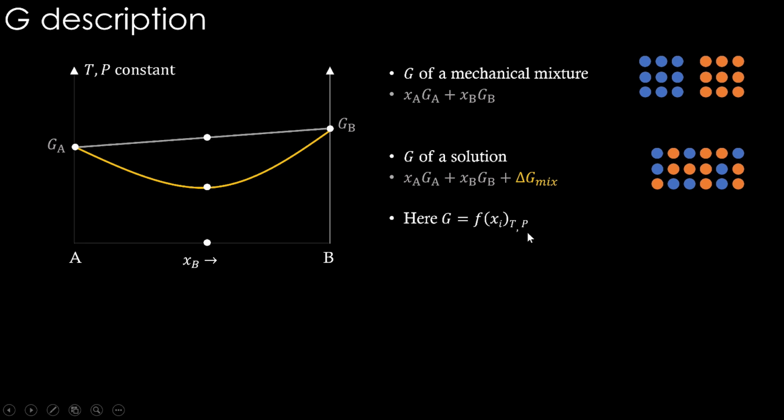Right? So here the mathematical representation is that Gibbs energy is a function of composition at constant temperature and pressure. But when we want Gibbs energy also as a function of temperature, we have just seen in the previous slide that the Gibbs energies of different phases change differently with respect to temperature. So we need Gibbs energy as a function of at least two things, composition and temperature, if not pressure. If the pressure dependency of Gibbs energy is also available, it is well and good, but at least we need Gibbs energy as a function of composition and temperature. So we need the mathematical description, basically equations for these different curves. And you know what we can do if the curves are available: at least one use you know now is that we can make phase diagrams out of it.